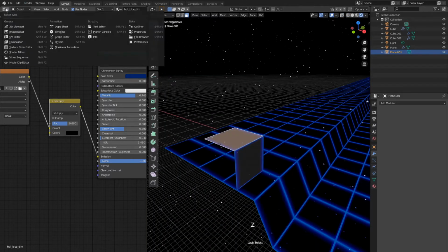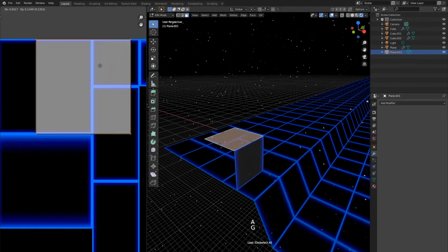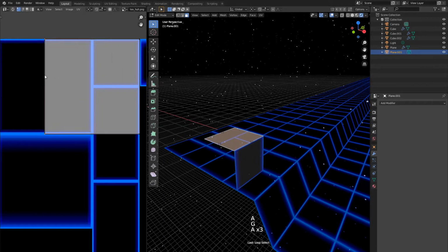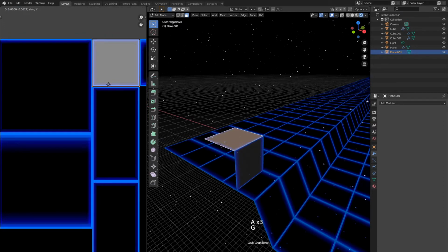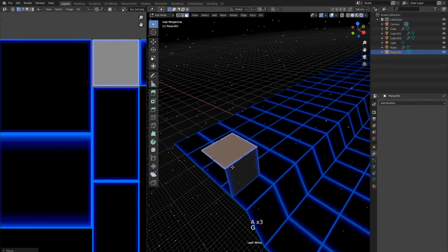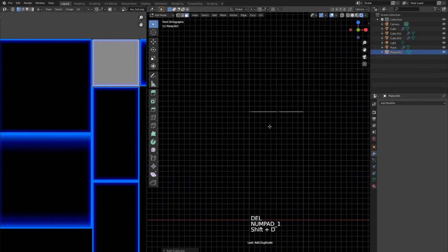Now switch to UV editor with top face selected. And let's remap it to a smaller square to make texture edges wider. Imagine doing that for each side after cube was already created. Now if we think, it will be much easier to copy an already UV remapped face than readjust each face manually. So let's get rid of that side face we created previously, and duplicate top face one more time. Continue building cube sides by using this amazing technique.